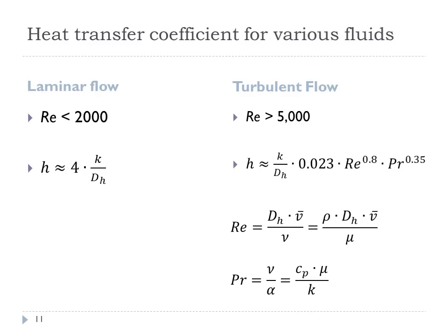So in the equation, there were the heat transfer coefficients, those H's. What I want to point out here is that H is a function of the Reynolds number of the flow. When you're in laminar flow, H has a fairly simple equation, laminar here meaning the Reynolds number is less than about 2,000.